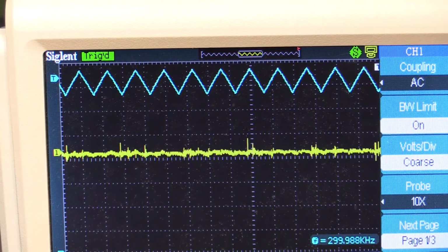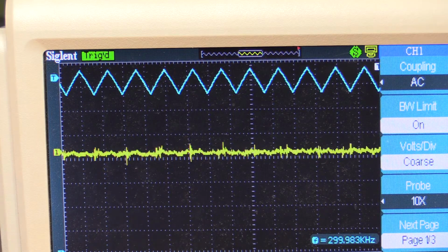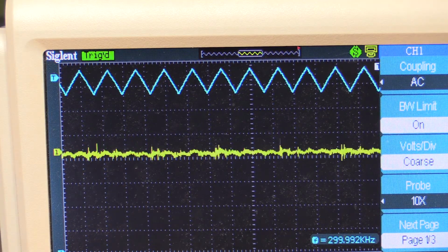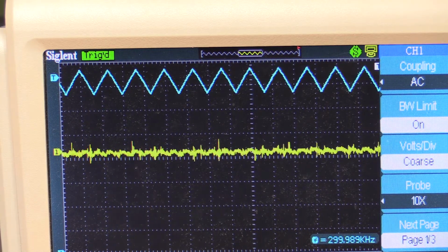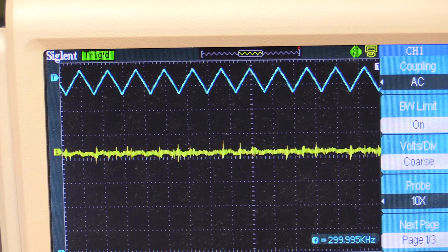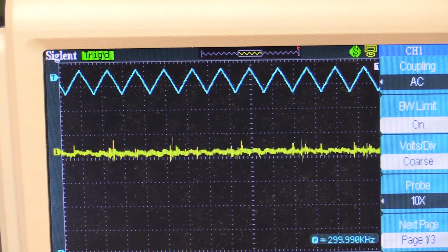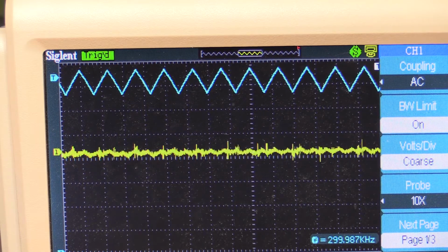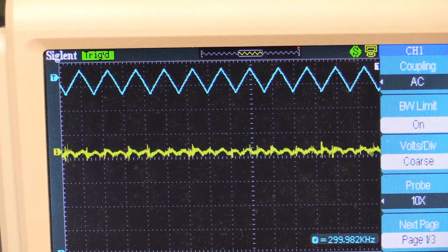So, you know what, I would give that, for any environment that I'm trying to use it for, probably a 10 out of 10. A little bit of extra DC coupling, maybe an inductor on the output to get rid of any transient noises from the Richtek. But as I say, I can't even measure what those transient noises are right now, because if I take the